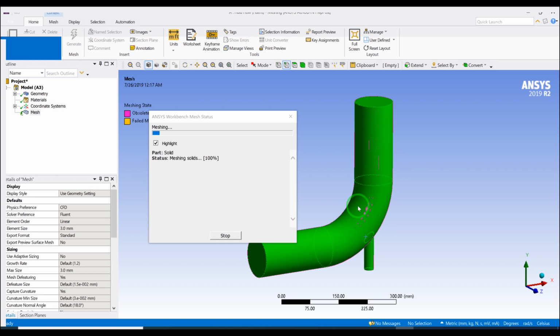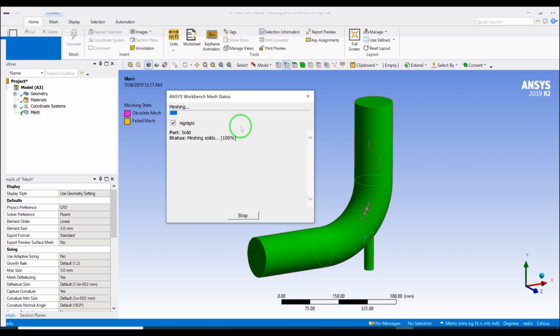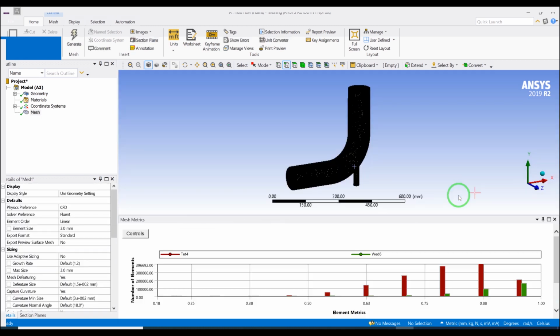So you can refer to references about the tetrahedral meshes and polyhedral meshes, to see what the benefits of those types of meshes are. And also if you use Fluent for meshing, the new Fluent has meshing, so you can directly create polyhedral meshes in Fluent too, which is a very powerful tool. So I will teach how to create Fluent meshes in future videos.